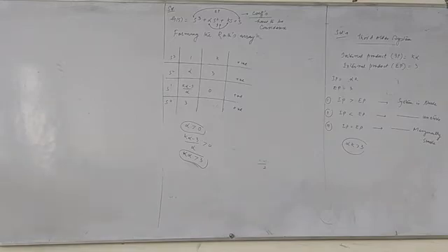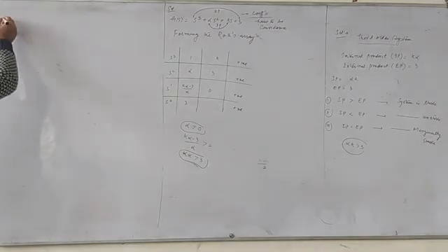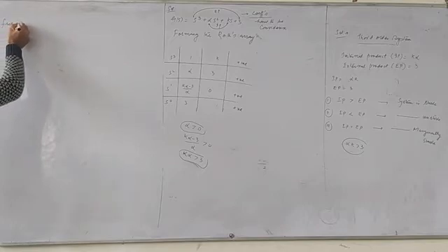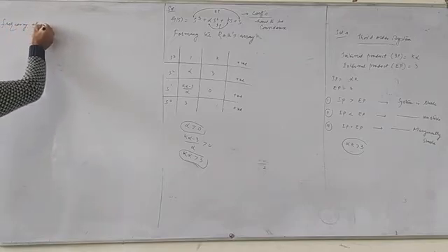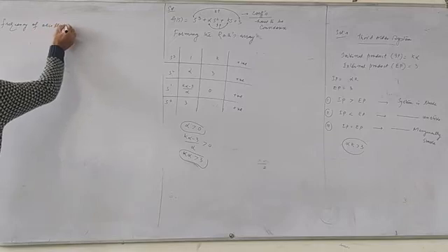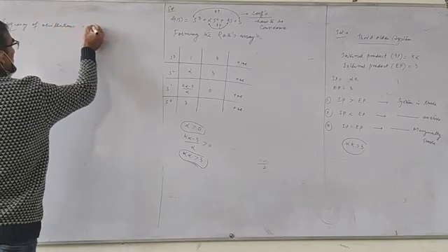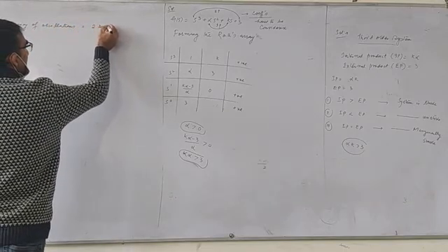So what does the 2 mean? They say the system oscillates at 2. There are 2 non-repeated roots, and which axis will they lie on? They will lie on the imaginary axis. So the frequency of oscillation is given, that is 2 radians per second.